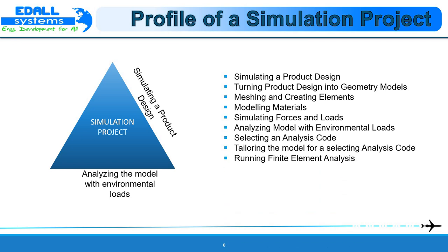Running finite element analysis. The analysis application provides the link between the Patran environment and the analysis solvers. These solvers can include MSC analysis codes, commercially available solvers, or proprietary codes developed by analysts for their own exclusive use. The analysis application provides the means to identify a desired analysis type, define translation and solution parameters, select a sequence of load cases, select desired output, send the model data to the analysis solver, and read result quantities from the result files.